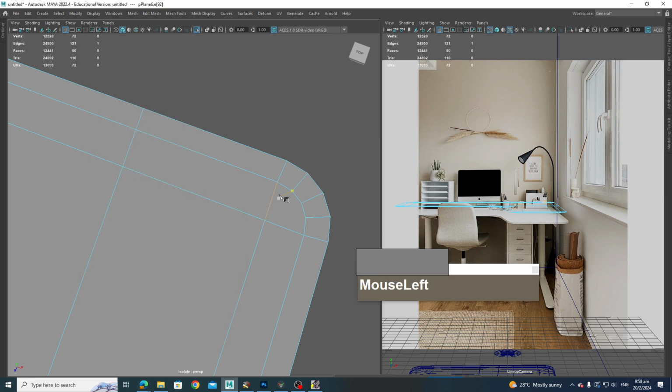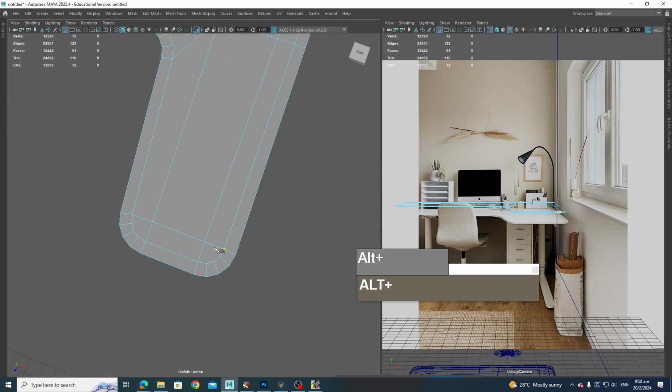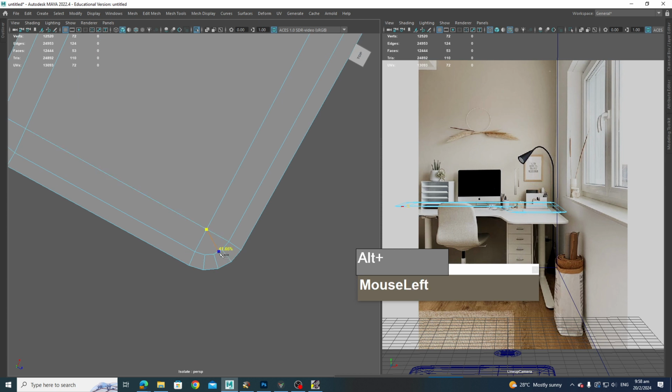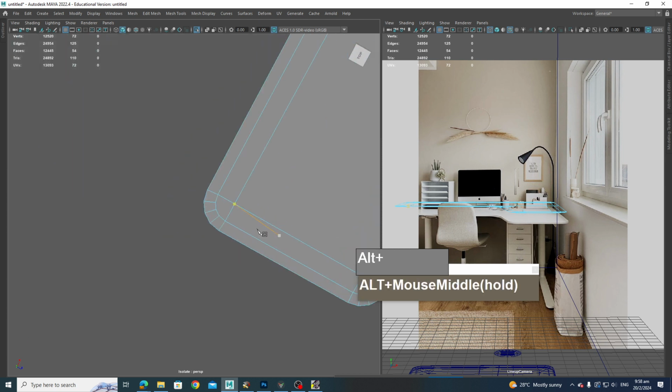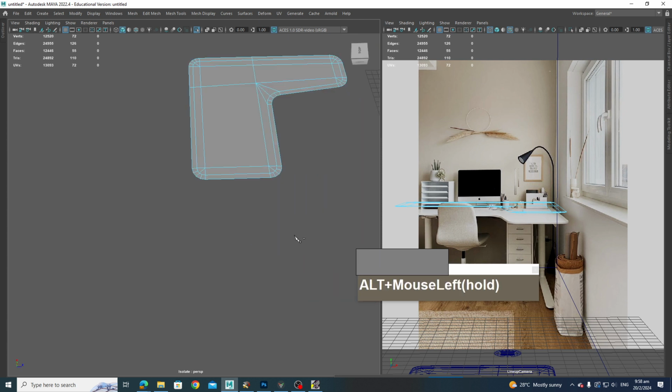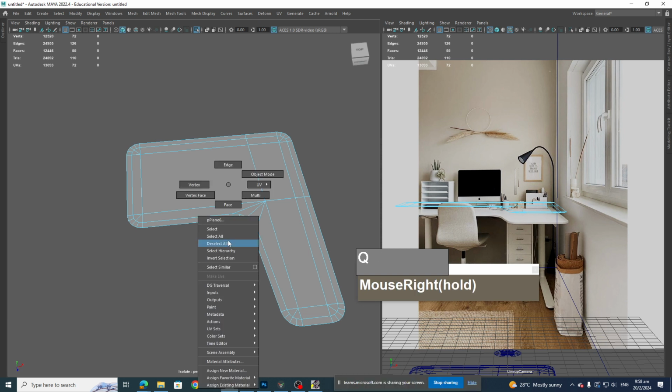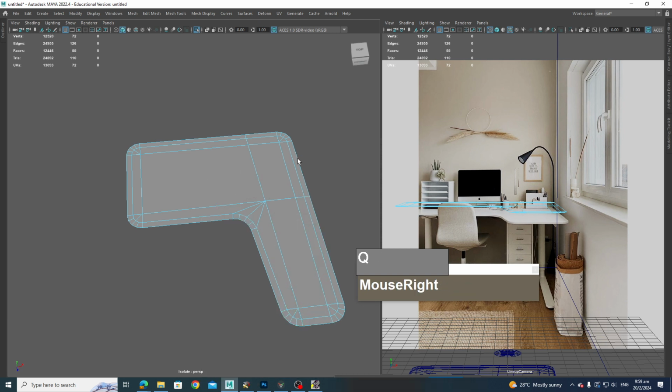Let's reset the tool. Cut from here to here. Okay, fix this corner from here to here. And from here, click and drag, press enter. Alright, that's it. We created a nice topology edge. And the good thing about this one is that we can select an edge loop across it, right? It should run continuously because everything is nice and four-sided.